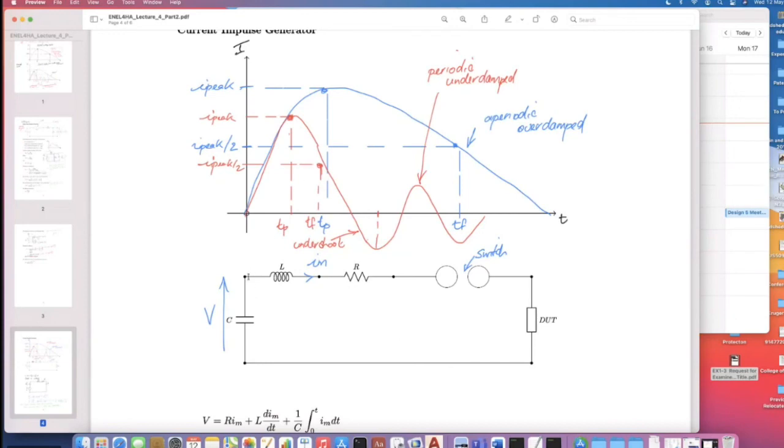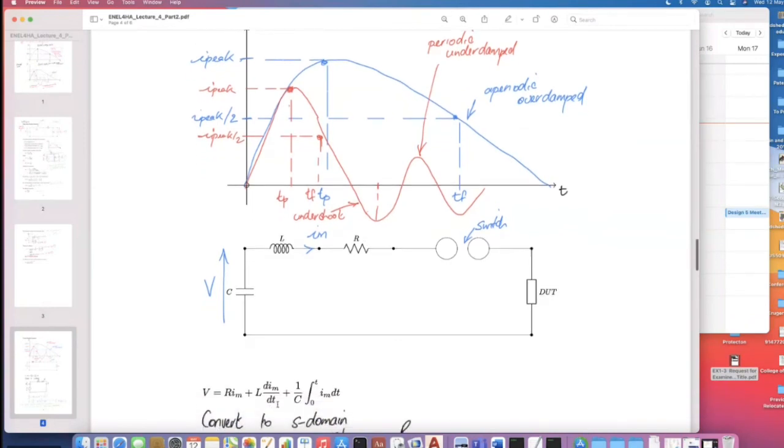So the region of times in this impulse generator are 4 microseconds, 8 microseconds. The problem with the impulse generators is that you can't get away from inductance. It inherently exists in any circuit. We can set a resistance, and we'll see how to set that a bit later. So we've got high currents in the kiloamps and very fast, so that L di/dt becomes very influential on the shape of the currents.